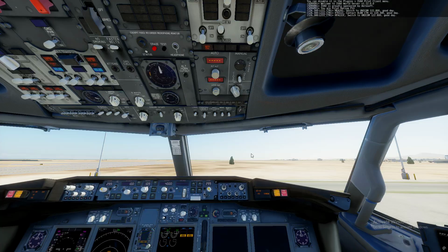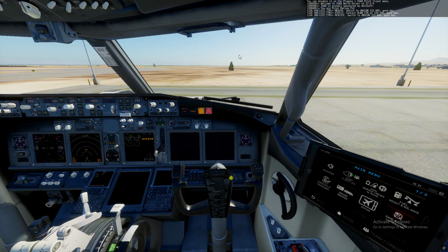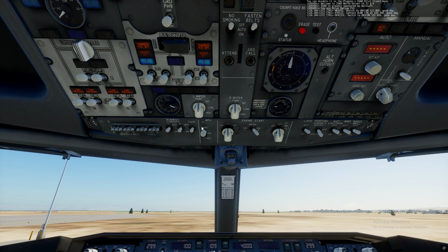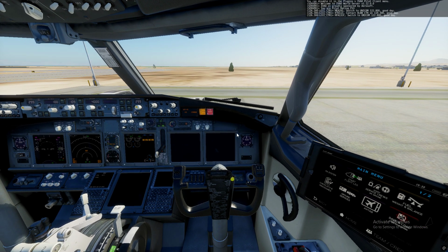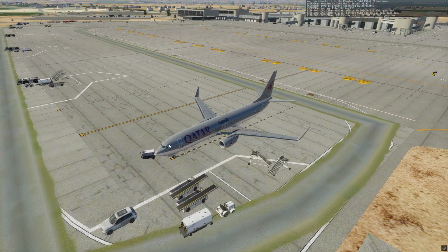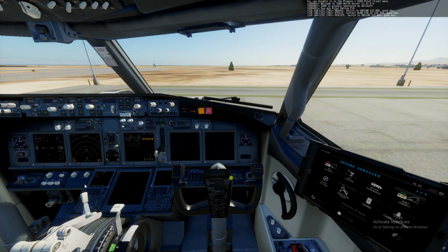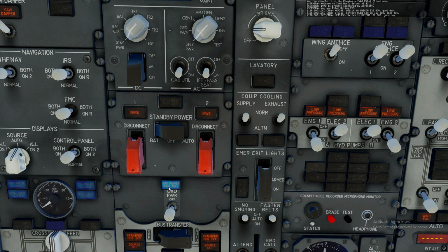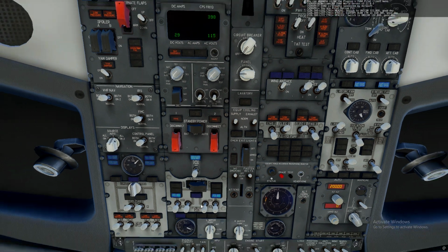In some airports at the gates they will have an external power source that they can hook to the airplane and give it power. Another way is to turn the APU on, which is a third engine located at the back of the aircraft. I will not use that now. There is another way, which is I can request a GPU, which is an external power source, and as you can see here, ground power available, and we switch to ground power.